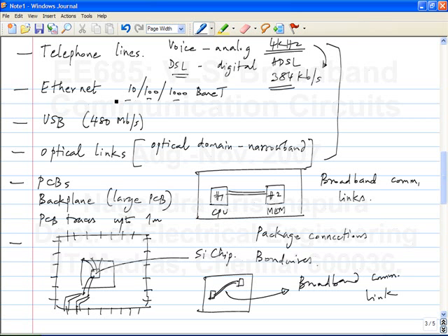Right? Similarly for Ethernet, if you look at the output of even a 100 megabits per second Ethernet line, you connect it to an oscilloscope and see, you will not see anything like this. Okay? Firstly, it's not a two-level digital data. One thing I have to say here is that digital data does not have to have just two levels. We don't need only binary digital data. You can have 5 levels or 7 levels or whatever. You use whatever is convenient. And it turns out that in gigabit Ethernet, you use 5 levels. Okay? But if you look at the output at the cable, you will not see 5 different levels. You will see a whole mess of things. Okay? And similarly for USB or any other case.